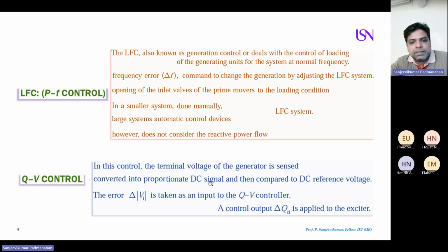We convert all these AC parameters into DC. So for example, I can give you a blind example. If you have a power on your generator of 10 megawatt, the voltage generated from the generator is say around 10 kV. All these 10 kV will be sensed by the sensors, and we convert it into a DC signal. Maybe the amplitude varies between 0 to 3.3 volt. But if you are using a DSP or another digital processor, it can go up to 0 to 5 volt DC.